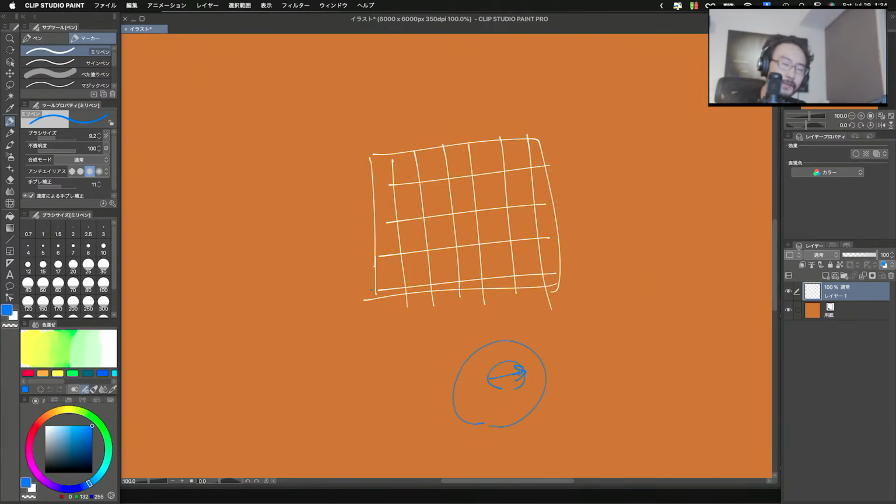Meaning if you want to create a plane out of this vector, the plane looks like a perpendicular grid, like that. So using the directional vector value as a normal for this plane, and by using this plane, you can slice the strip by just providing the vector value and the center of this plane. Okay.